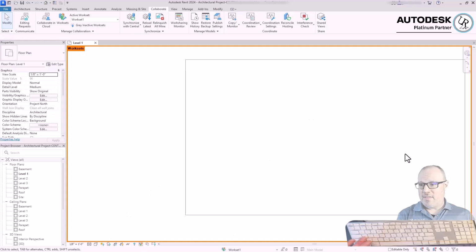Now that everything has been disabled in the view visibly, that means everything is not on work set 1 any longer, and work set 1 is now empty of content. Work set 1 is also required to exist, very similar to, again, layer 0, but you don't have to have anything placed on it for it to exist.